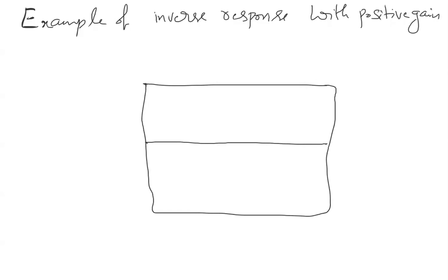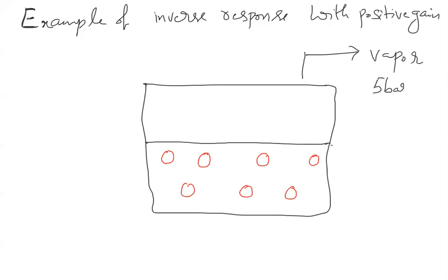See, boiler, what comes is you are getting a vapor here. The boiler has vapor droplets. Suppose you are generating steam at, let's say, 5 bar, then what is the boiling temperature? How do you know the boiling point corresponds to 5 bar? It is just 5 power 1.25, a thumb rule.